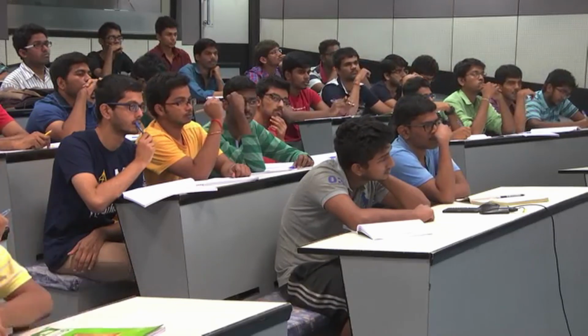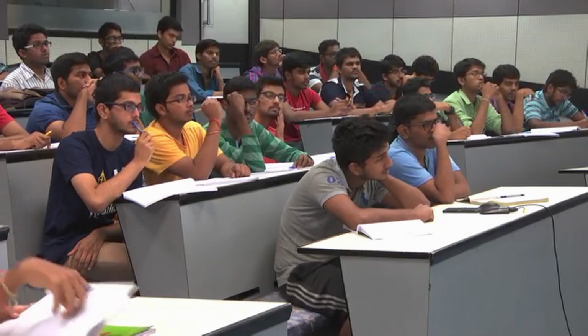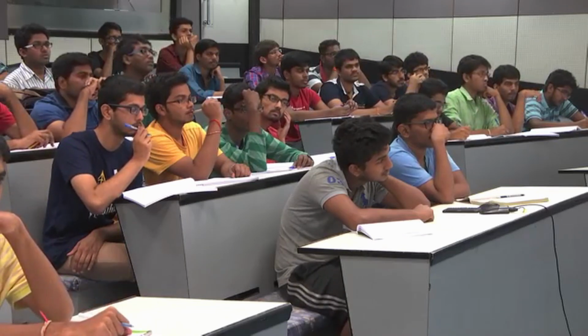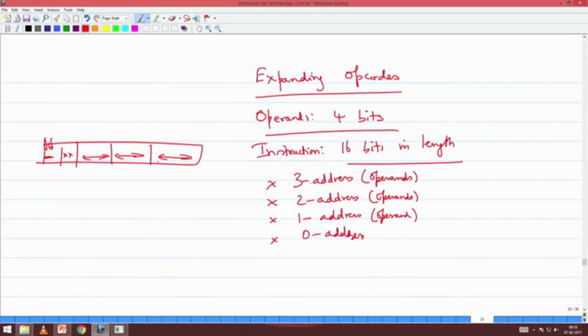Now can you tell me how many 3 address operand and 2 address operand instructions, how many of each kind can I have? The moment I say 2 bits are used to specify the number of operands, I could have maximum 4 here.